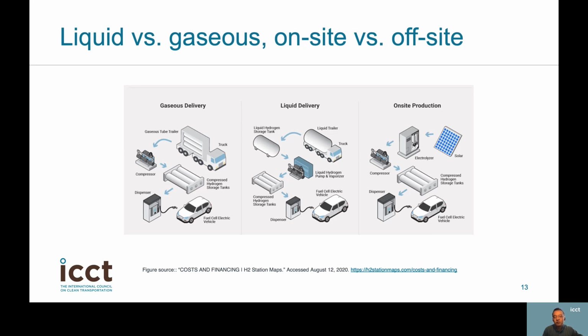Also, cryogenic storage at stations may use cheaper equipment by avoiding tube trailers and compressors, especially on a per kilogram hydrogen basis. For heavy-duty applications like buses, liquid delivery makes more sense economically because a centralized hydrogen liquefaction saves energy for the compression stage and purifies the fuel as impurities sink to the bottom. Gaseous hydrogen production and delivery solutions are increasingly looking like a niche market for low-volume, low-frequency uses.